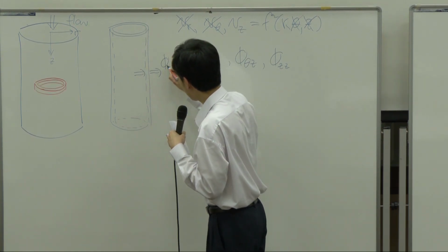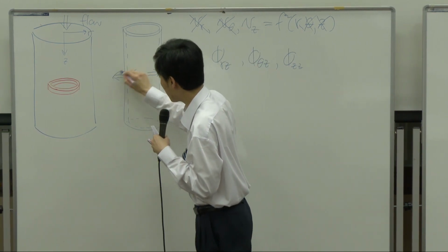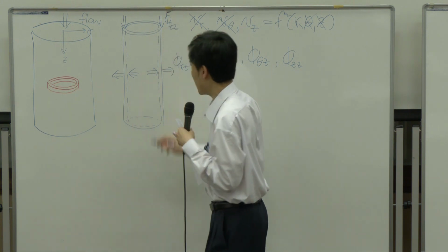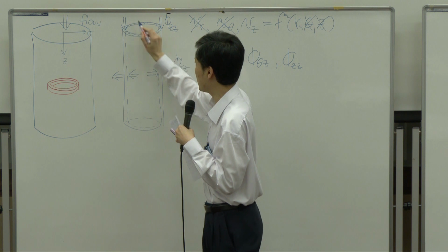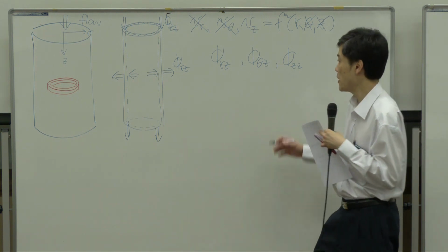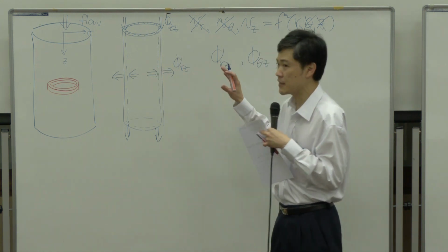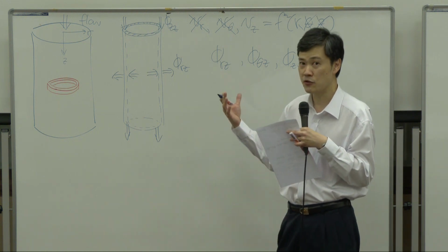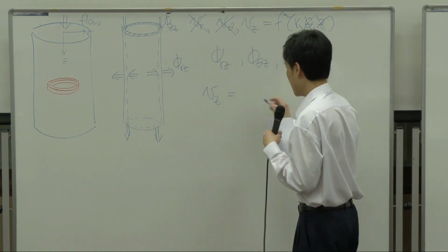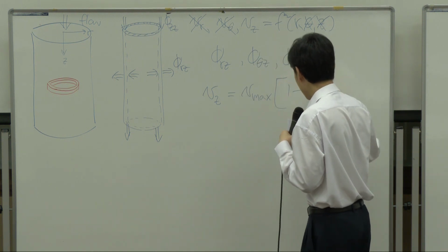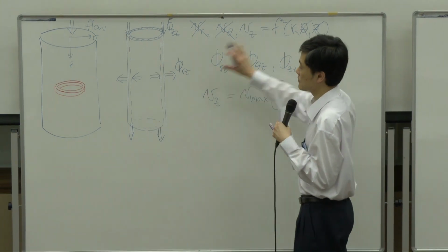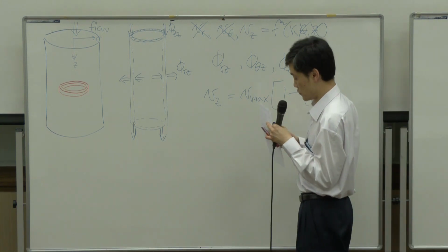Here it looks like this. This would be your flux Rz going from the center of the pipe toward the outer rim of the pipe, and that would be flux Vz going in on this circumference, on this annular ring of the shell, and going out at the bottom. Okay? This is exactly what we have done in chapter 2. If you set up the momentum balance like so, assuming density and viscosity are not functions of temperature, it means that you do the calculation as if the system is isothermal. Then you end up with the velocity profile Vz equal to V maximum times 1 minus R over capital R squared, exactly the same as we did earlier in chapter 2. So once all the calculation based on momentum is done, we can move on to energy balance.